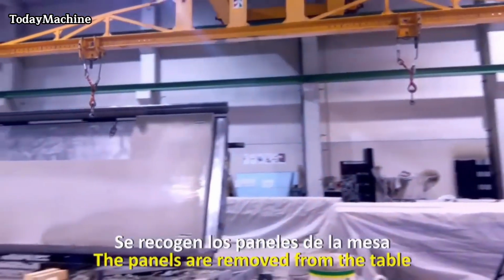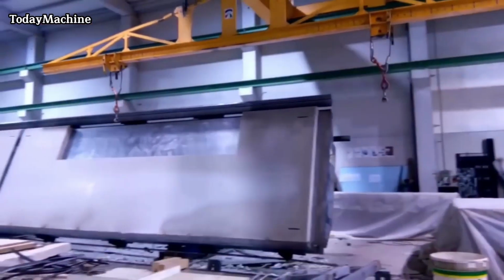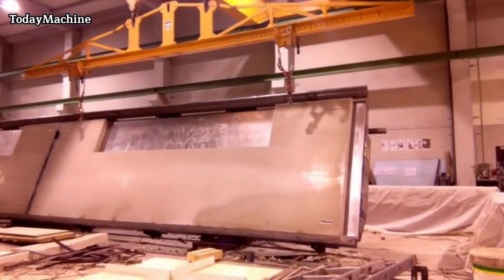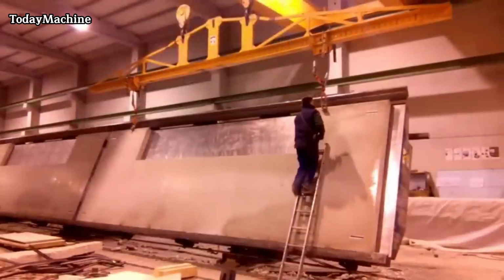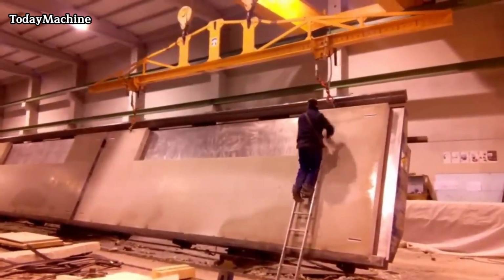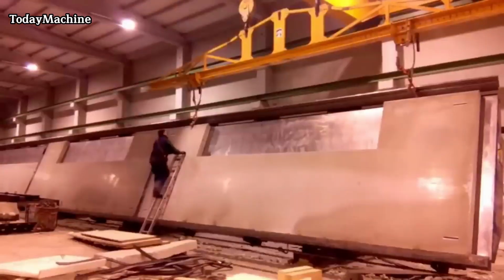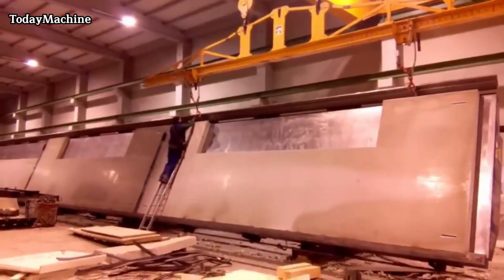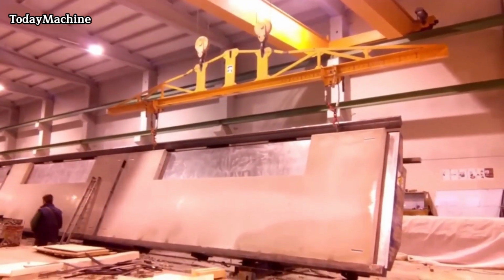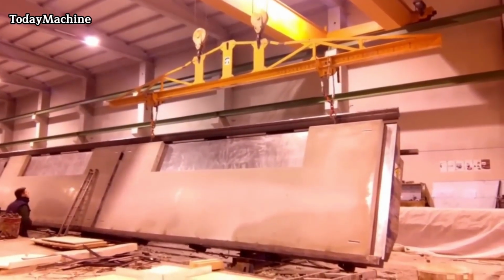With the separators removed, the precast panels are ready to be lifted and removed from the tilting table. Handling equipment, such as cranes or hoists, is used to safely lift and transfer the panels to the designated area. The handling nails that were strategically placed earlier facilitate this process, ensuring that the panels are securely held during removal and transportation.